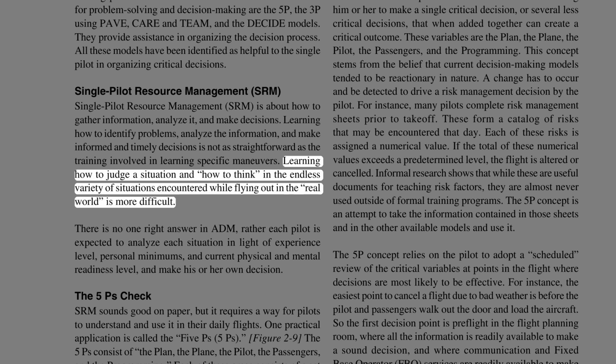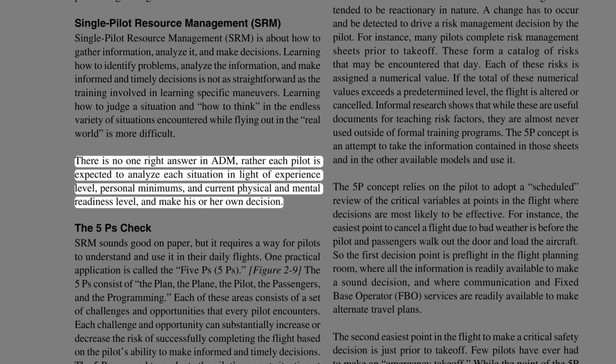Learning how to judge a situation and how to think in the endless variety of situations encountered while flying out in the real world is more difficult. There is no one right answer in ADM. Rather, each pilot is expected to analyze each situation in light of experience level, personal minimums, and current physical and mental readiness level, and make his or her own decision.